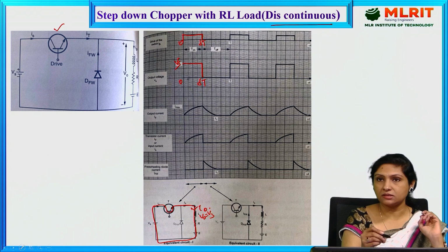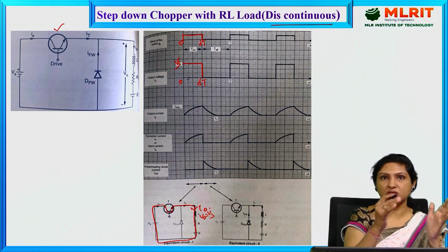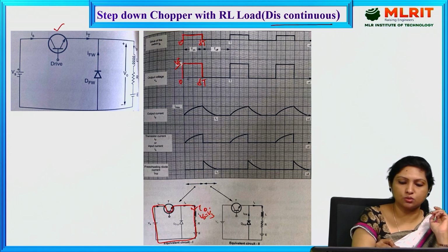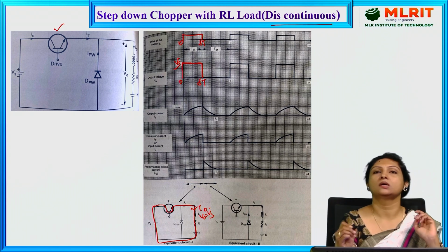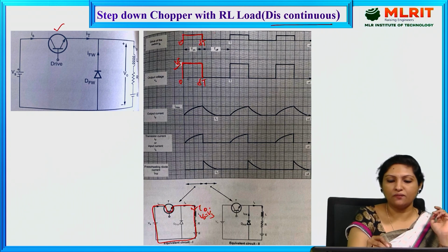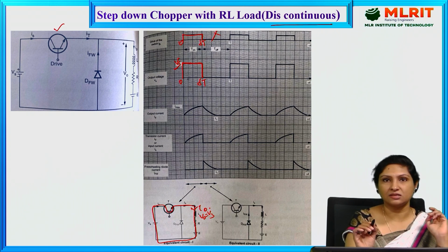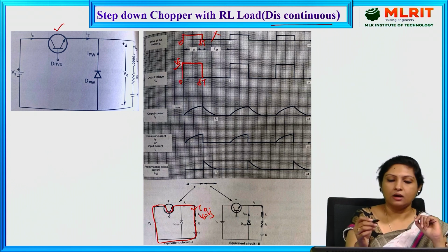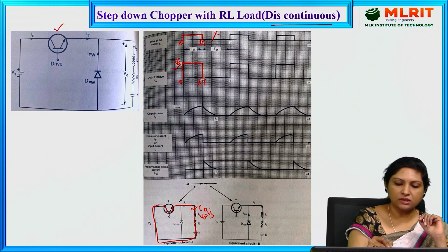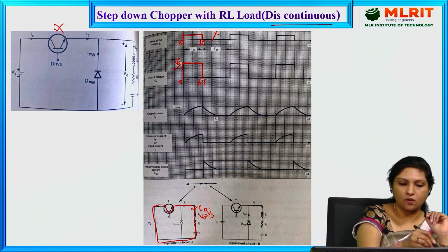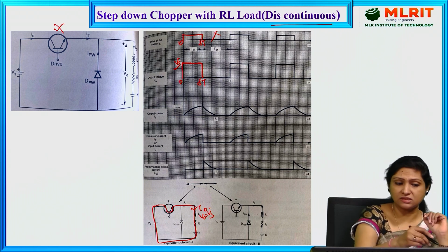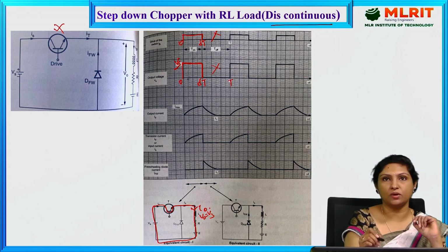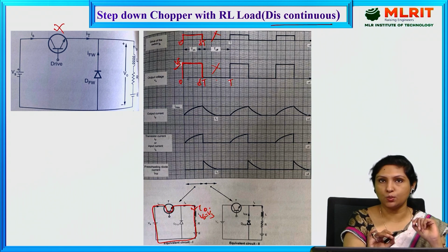Since the transistor is turned on, supply voltage is connected across the output, and that is how we are getting the output voltage from 0 to delta T with magnitude Vs. And the moment it reaches delta T, we have withdrawn the base drive, and hence the transistor is turned off. And since we are making use of an inductor, because the transistor is turned off from delta T to T, there is no output voltage waveform. Here, V0 average is equal to 0.